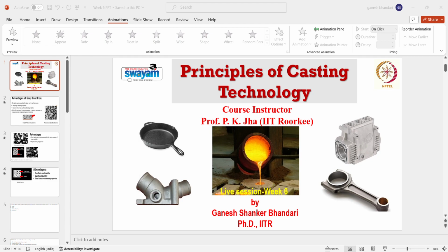So when you go with rapid cooling of that iron, it will not have that much time for the carbon to diffuse out from the structure of iron carbide. So it will remain in the form of iron carbide only, and then you are going to get your white cast iron. But if you give sufficient time during the cooling process, say if we go with an annealing process, then you are going to form gray cast iron.